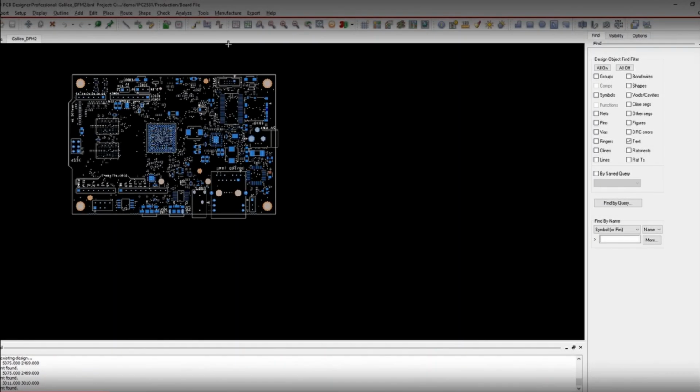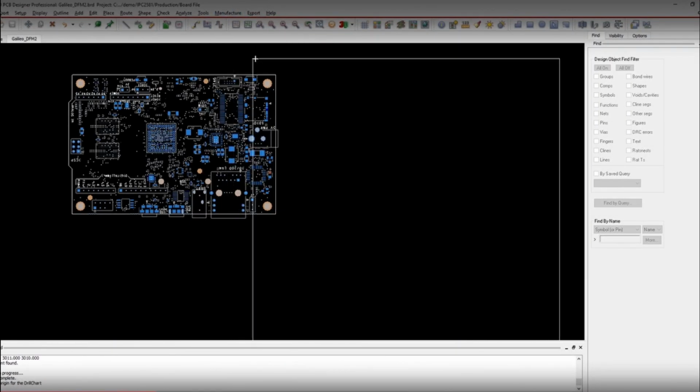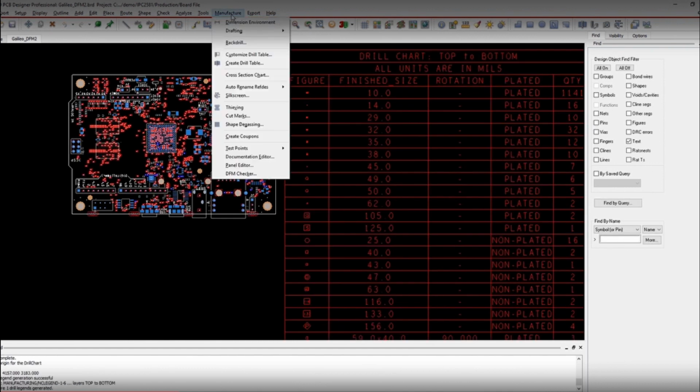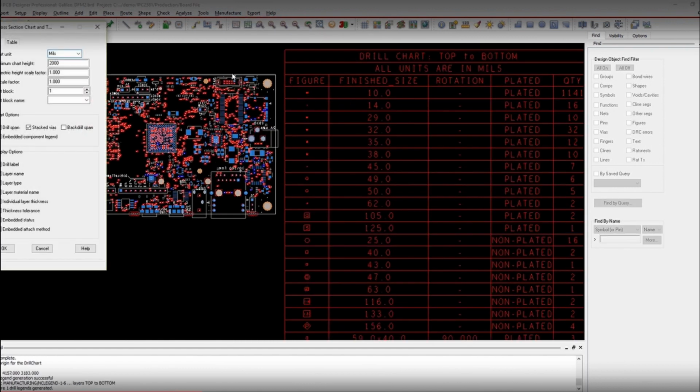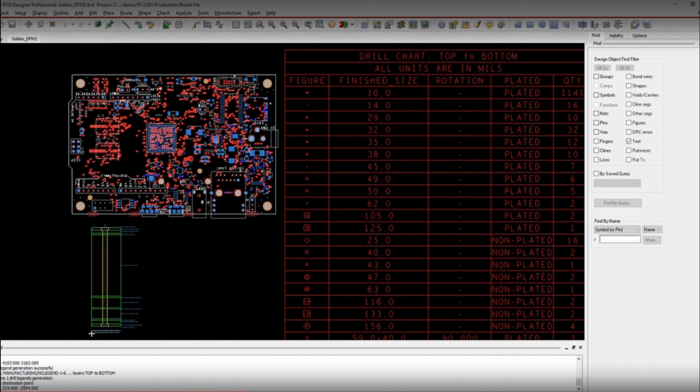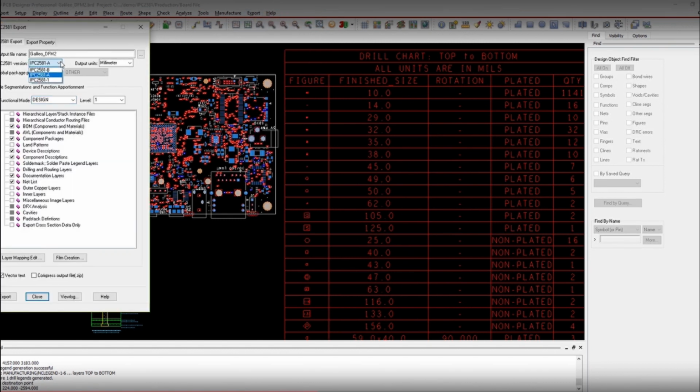Manually maintaining manufacturing files like Gerber, drill files, netlist, and more is bound to lead to mistakes. IPC 2581 combines all necessary PCB manufacturing data into a single file so you can easily communicate your design intent to your manufacturer and get your design manufactured accurately. With default configurations and presets, you can easily select from a list of fabrication, assembly, or custom outputs to fit both you and your fabricator's needs.